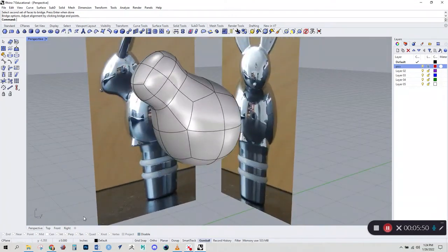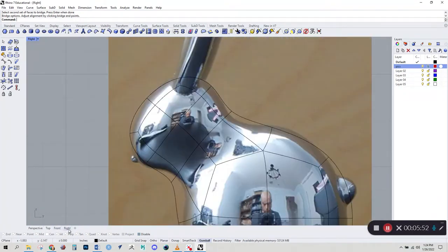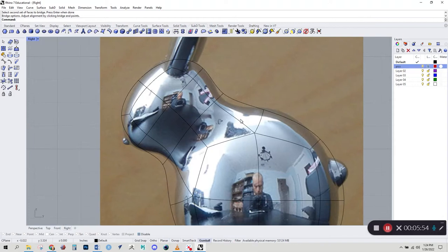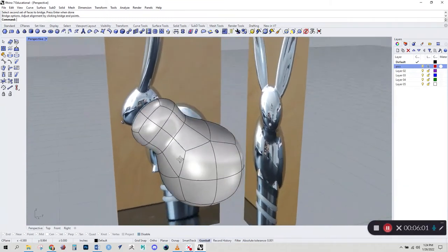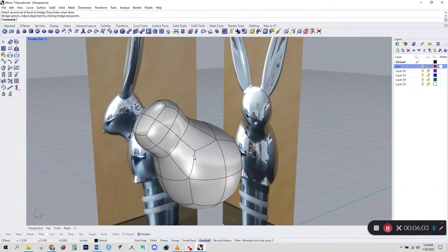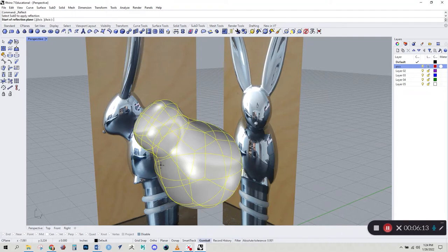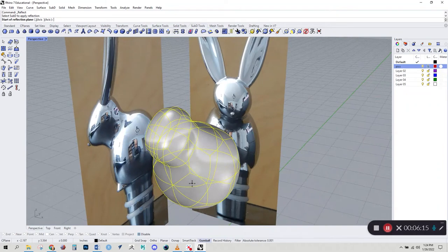All right, and let's go back into the right viewport. And actually, before I even get into modifying these things, let me go ahead and add symmetry to the model. That'll make everything that follows a little bit easier. So we will come up to, where is it? Reflect SUBD object. We'll click on that button. And this is the object we want to apply the symmetry to.